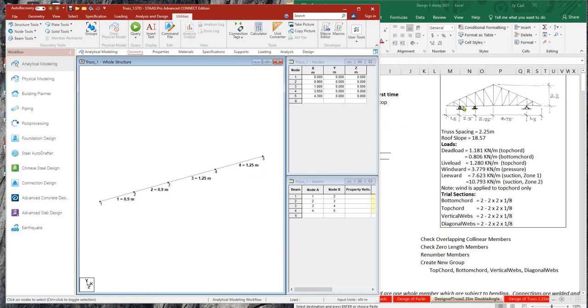Which corresponds to this. Now, you can also measure using the ruler. So, go to utilities and then node tools. You will see here the node to node distance. So, you just click that. Let's measure if this is 1.8 and this is 2.5. Okay, so click this, then 1.8. Then this is 2.5. Alright. Or another method of producing this is to insert nodes.